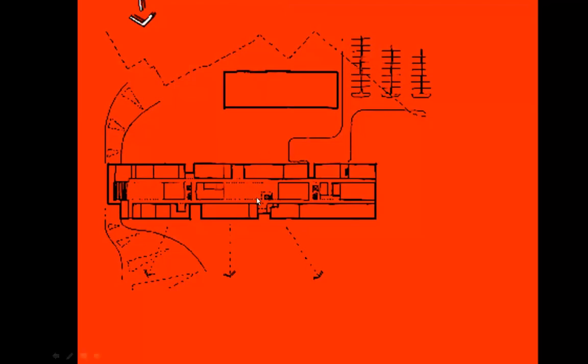You will then be starting with a much more controllable situation in terms of solar control and daylighting. Now, we were lucky on this site because we could orientate the primary facade facing due south, which was the absolute ideal. We then also have another facade facing north, which is also an optimum situation for this type of building.